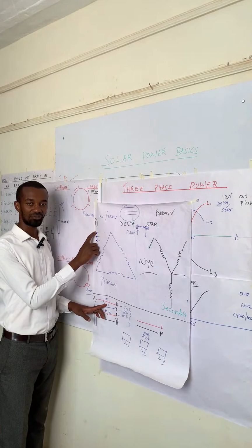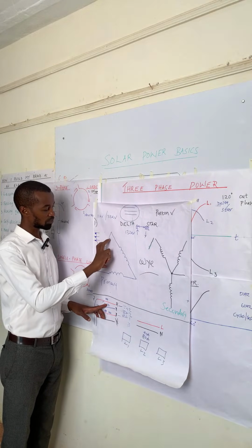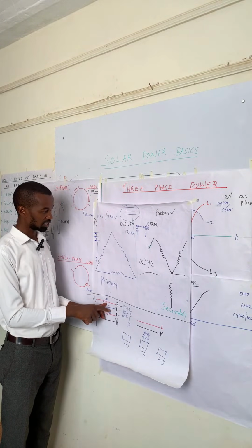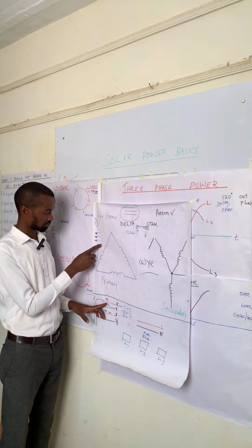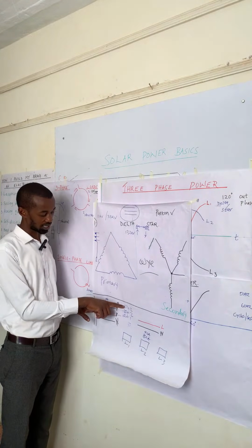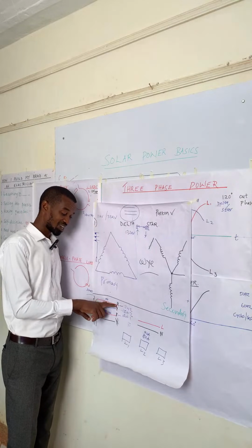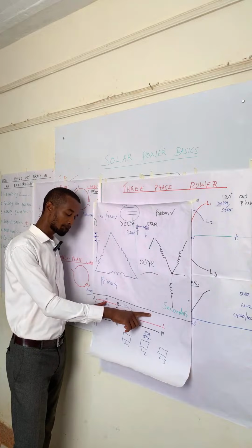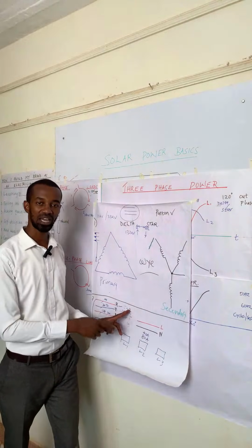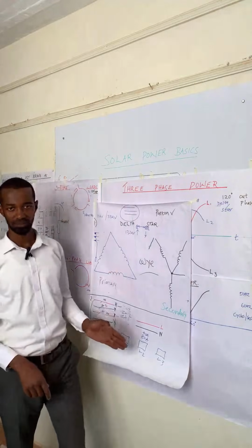For instance, if a high tension power line supposed to be connected to the primary gets in contact with a low voltage power line, it will induce that voltage into the low voltage line going to the customer. That voltage will travel to the customer's home and appliances, and definitely cannot be stopped by a fridge guard, TV guard, or an AVS 30, and it will damage their appliances.